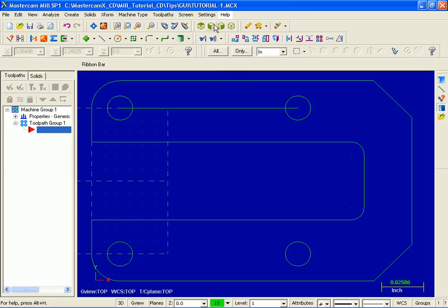Now down below we have a selection of toolbar icons, and if you cast your eyes over to the right hand side we have the MRU. Now MRU stands for most recently used toolbar, which presently is vertically docked. Now if I hover over this top icon, and you can see customize, that was the last function that we were in, and down below create line endpoint, that was the one prior to customize, and then down below that analyze distance. So this is the MRU, most recently used toolbar.